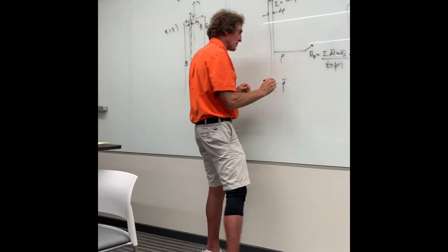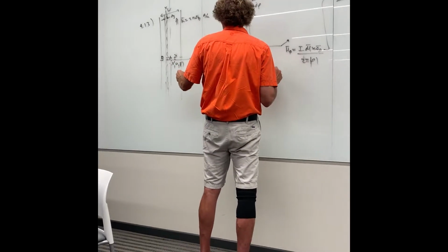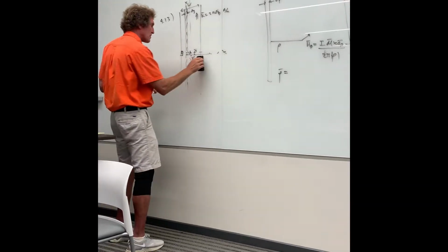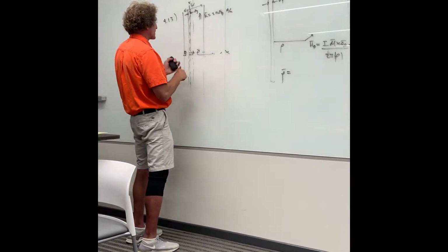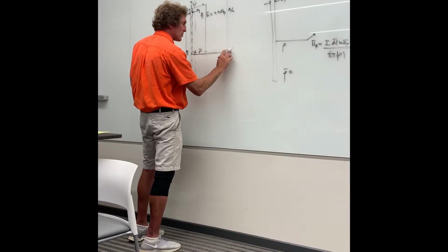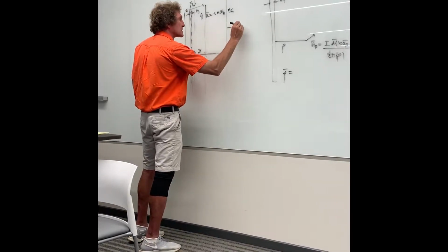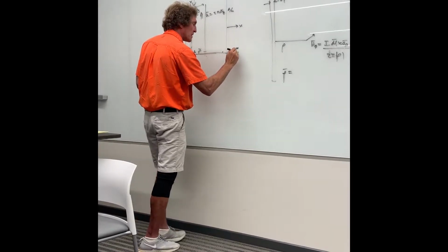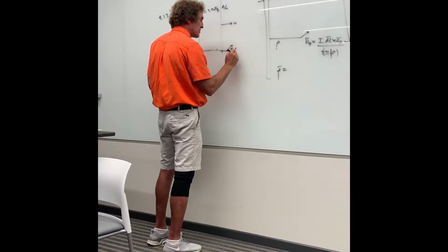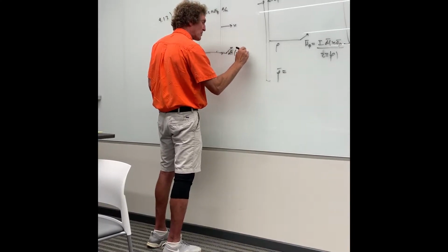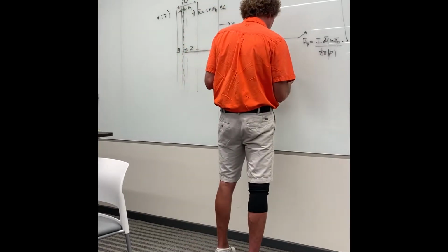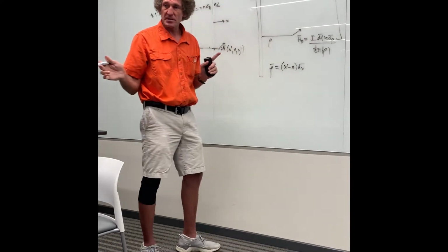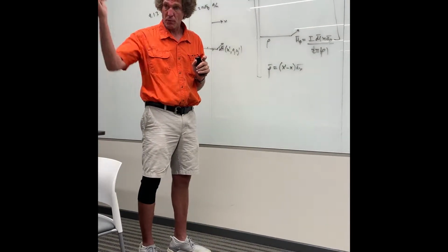So when we look at rho, first it's the position of observation of the field. Let me make this a little clearer. I'm going to say that my rho vector from this goes to a point, that is the x-axis. It's going to go to a point of observation where I want the H field, or I want dH. And this dH is at a point x prime, 0, z prime. So that means rho would be x prime minus x, a_x. Do you follow me? I'm going to do this in Cartesian. Everybody? Follow me?